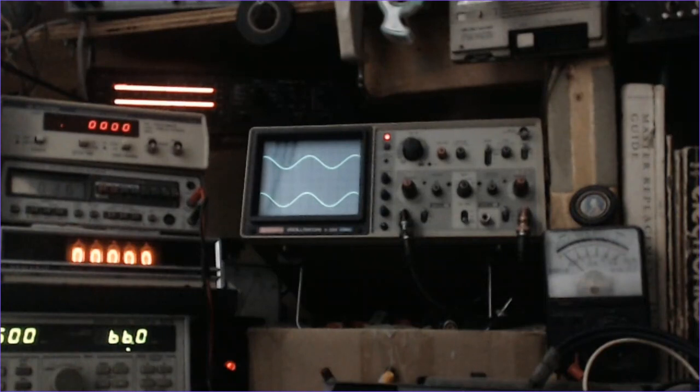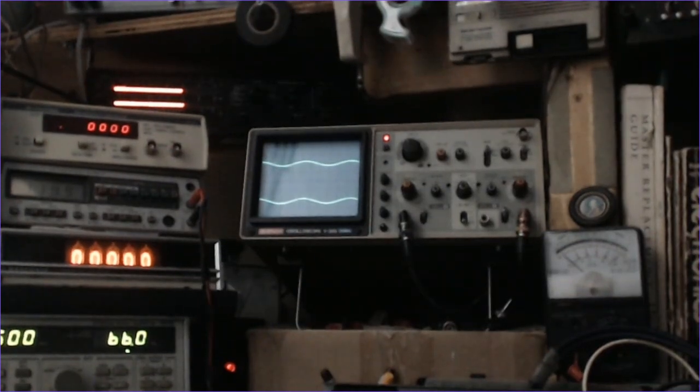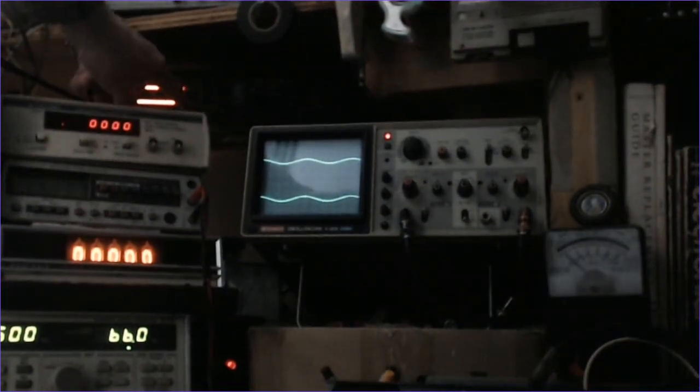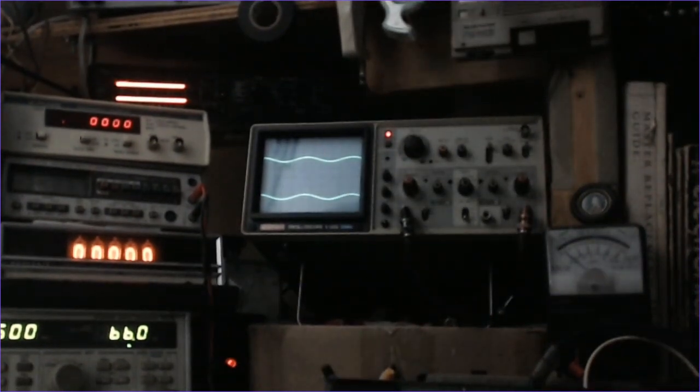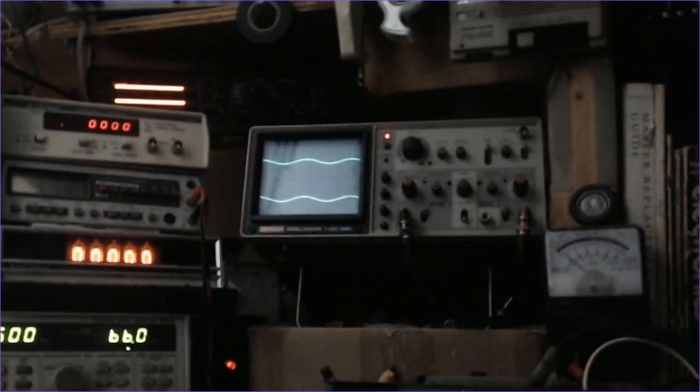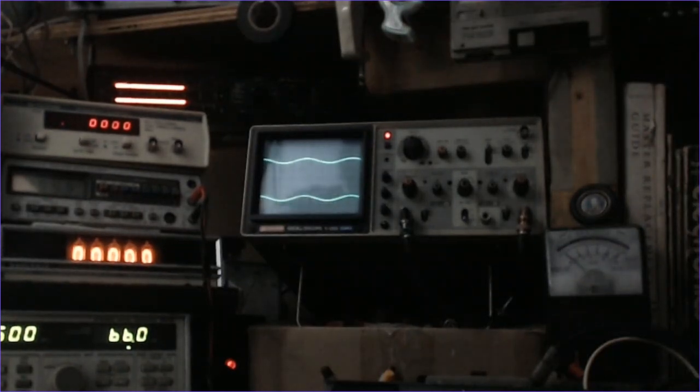The other thing we're going to do is do a frequency response test. And for this, we want to really look at the bar graph up here. And we want to make sure as we go through the different frequencies that it doesn't change appreciably. It might change a half a decibel or a decibel over the entire range.